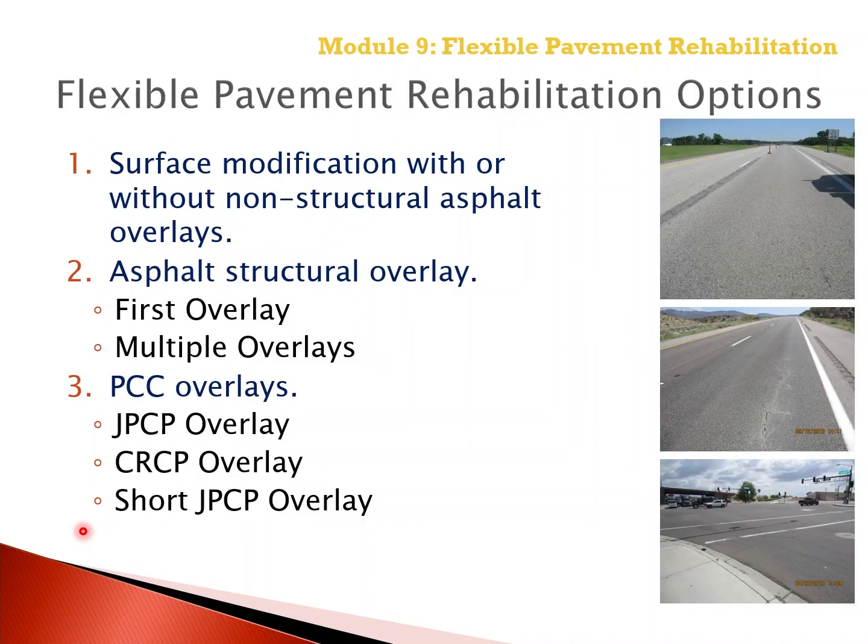Now, the flexible pavement rehabilitation options can be grouped into three basic design strategies. The first is surface modifications with or without non-structural asphalt overlays. In other words, the pavement is considered to be structurally adequate, with very minimal levels of distress.